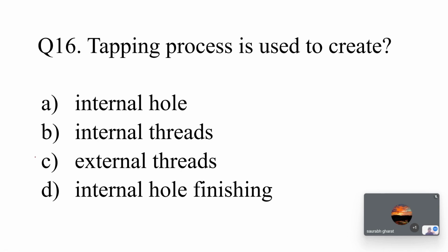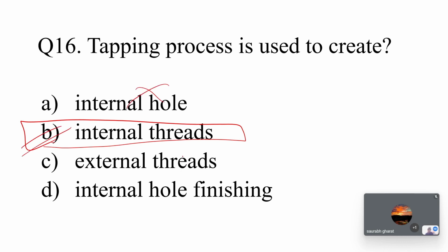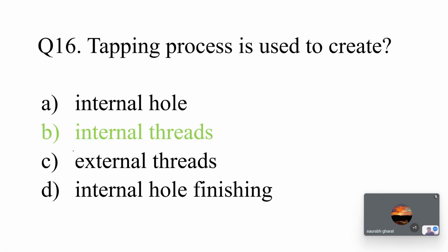The correct answer is internal threads. Internal holes are made with drill bits, external threads are made by a turning operation, and hole finishing is different. Hole finishing you do with reaming, not the tapping process. So internal threads is the only correct option here.